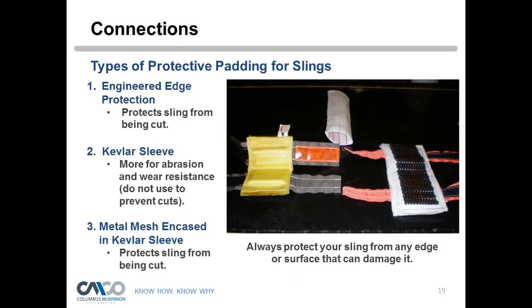I have a really quick question for you. I'm just curious, is there a difference between hoist chain and alloy rigging chain? Oh yes, absolutely. That's a really good question as well. Hoist chain and alloy rigging chain are two drastically different types of chain. For rigging chain, we recommend using alloy rigging chain only. There are grade 80, grade 100 out there, and there's even a grade 120 out there.